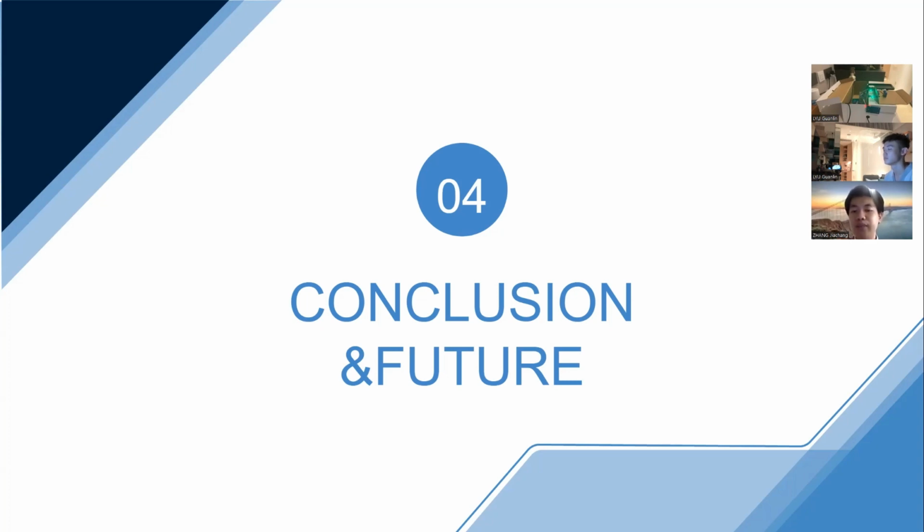Say, let it read multiple cards within a very short period of time, store the values it read, and make a comparison with the authorized UID. It should not warn immediately if an unseen card is sensed, but rather after reading all cards, and then if there is no authorized card, give a warning.